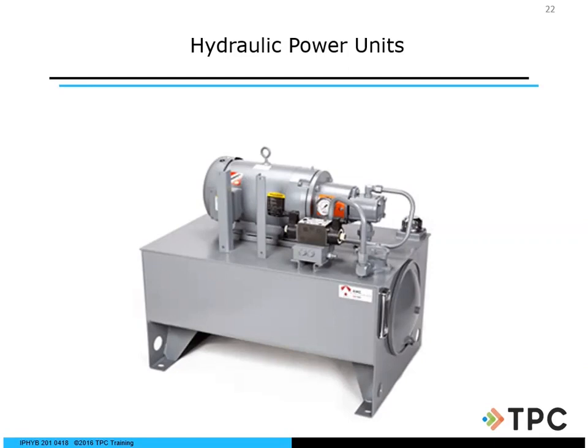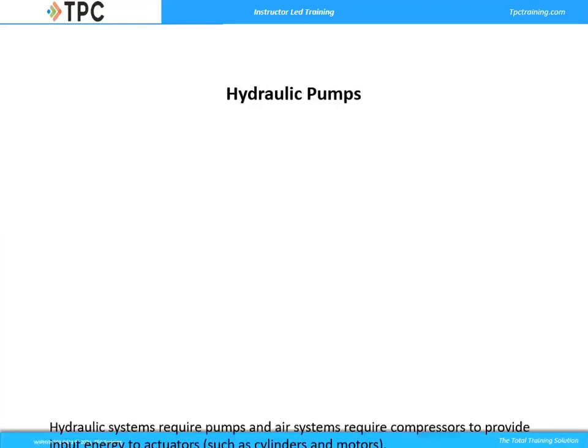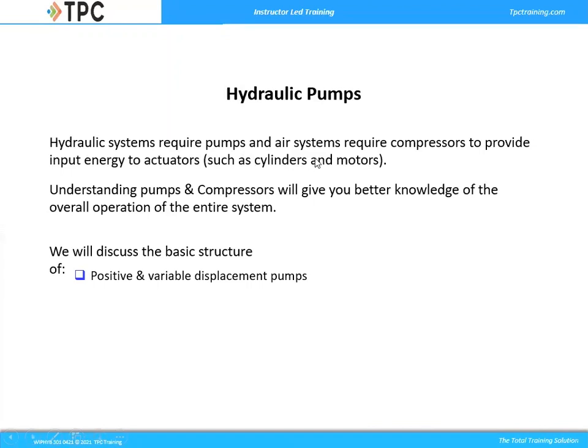Keeping your reservoirs clean is critical all the way through. So we've got a motor and a pump, or our main hose. There's baffles on the inside of here as well. These are some of the things that you really need to take a look at. What type of pump? It all depends upon our application. We have some internal and external gear pumps throughout our system. Hydraulic systems require pumps, and pneumatic systems require compressors to provide input energy to the actuators. Understanding pumps gives you a better knowledge of the overall operation of your entire system.